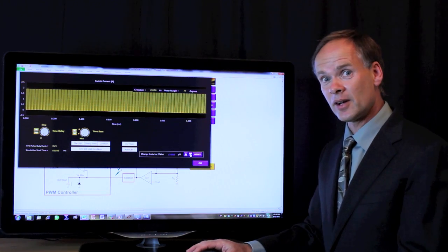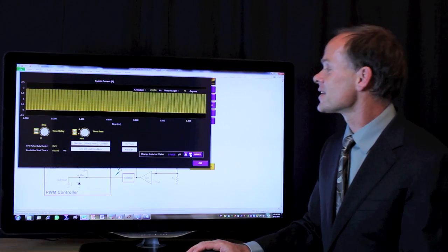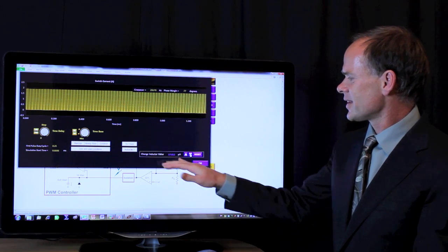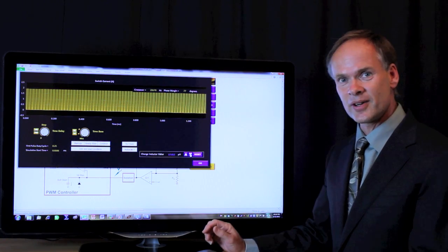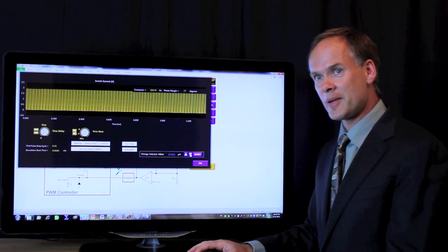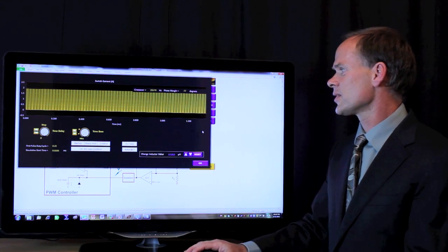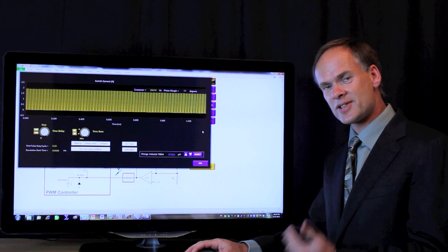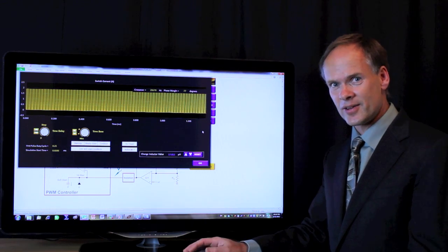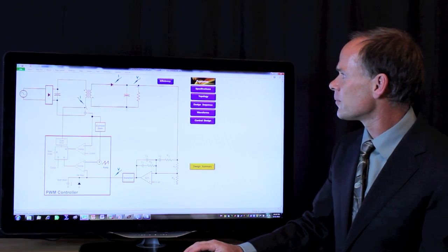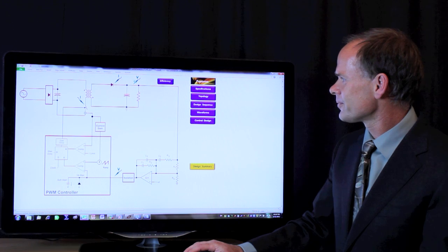This would take a long, long time running this in Spice. Now, one thing that's happening here, which is very interesting, is when I change the inductor value for the simulation, the control loop is automatically being recompensated. So when I look at the transient response with the new inductor value, it's the transient response with the best controller on it that you can achieve.